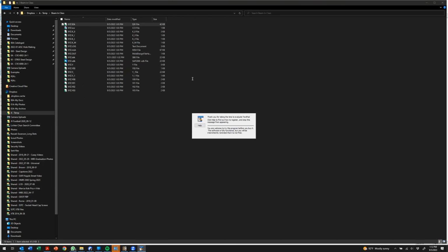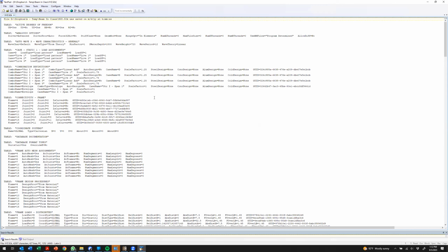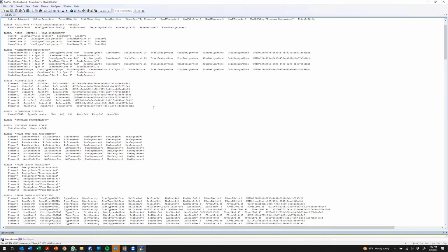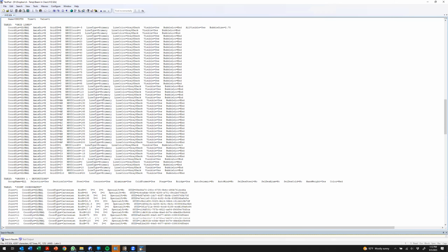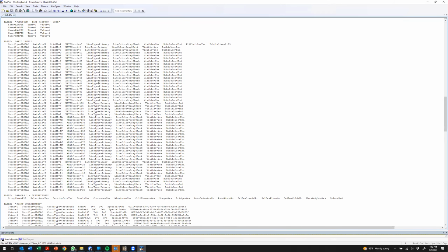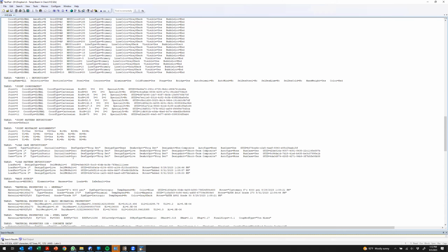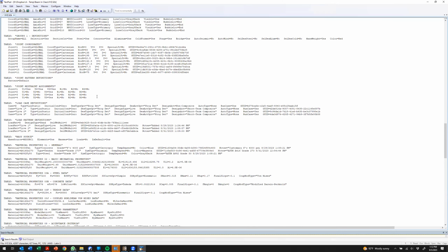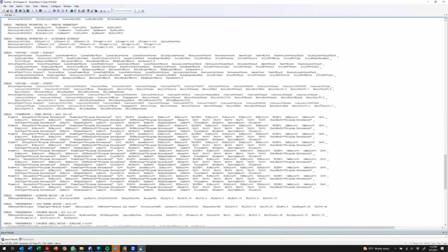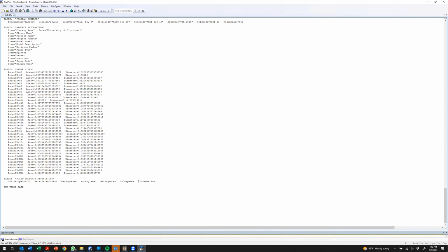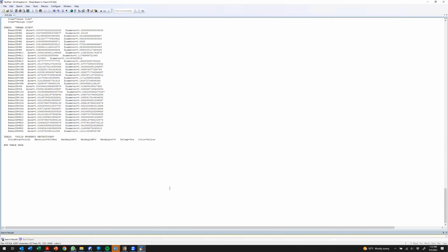then what that does is it gives you a text description of everything that's in your finite element model, everything that's in your computer model. It gives the coordinates of the grid lines, the coordinates of the nodes, whether the nodes are restrained or not, the load case definitions, the load pattern definitions, the load combination definitions.